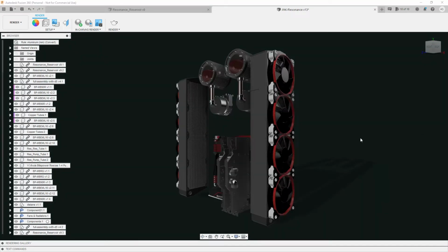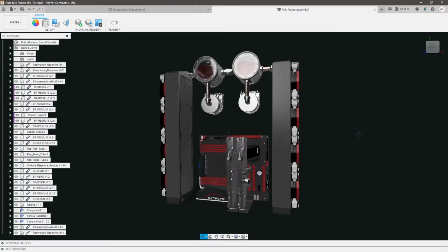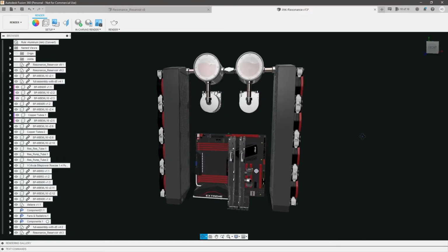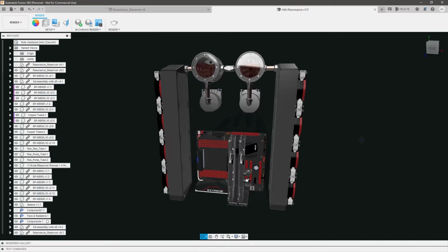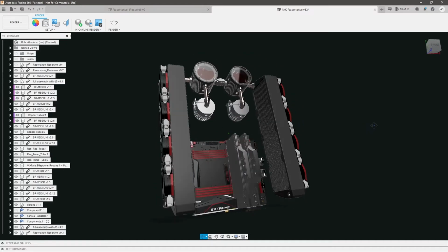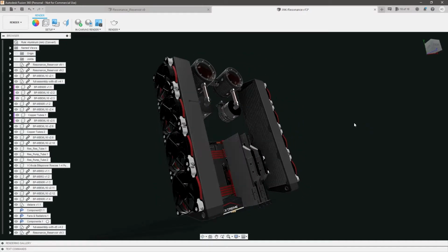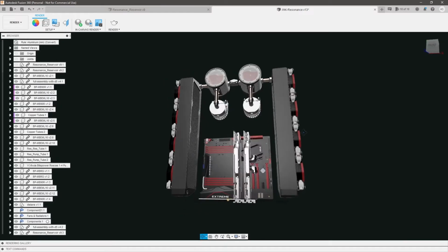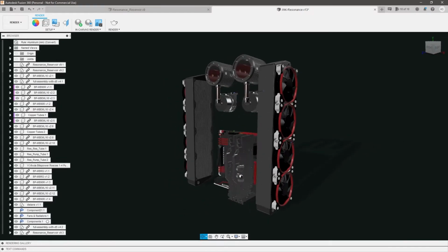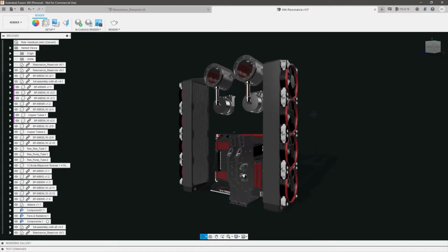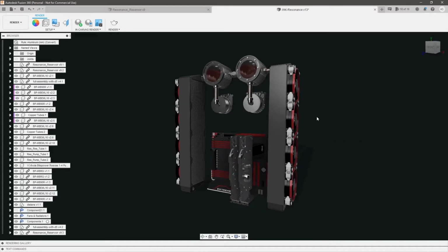Okay, so jumping into Fusion, we are going to cover primarily bottom-up design today, because Fusion 360 is natively a top-down design software, so most of you are already using a top-down approach in your designs. So what we really need to figure out is how can we utilize a bottom-up approach to enhance our designs and make modeling changes between different designs much more streamlined.